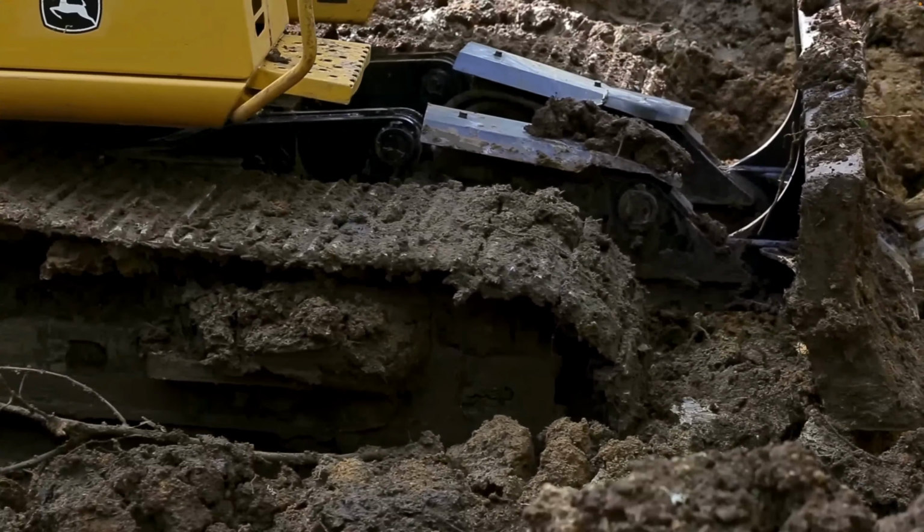As we build the dam up, we get to a point where we can be looking at the connection to our spillway. And so once we have built up to that ultimate dam height, we can cut that spillway into the side of the dam, into the native soil of the side slope of the valley. And that then gets built with the same 2-to-1 slopes on the outside and a flat bottom, and designed so that it can pass that water well around the dam. You never want to build a spillway over the top of a constructed dam, as it will erode the dam.